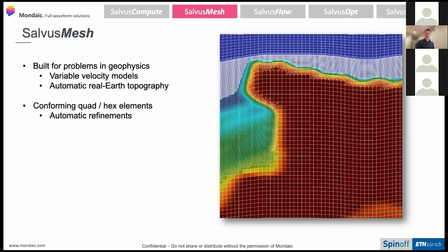And what's also been pretty neat and quite important is this whole focus on local and automatic mesh refinement techniques. So what you're looking at on the screen right now is a classical example that you might have in exploration geophysics, where we have an oceanic layer on top. That's the blue elements that are relatively big. And then we have an extremely slow velocity sediment layer just below the seabed. Now, of course, usually if we want a conforming mesh and we want to ensure that we maintain the advantages of explicit time stepping, we would either need to set the entire mesh to the resolution of the wavelengths that are present in the slow velocity layer, or we can go ahead and just do local refinements to basically not do computational overkill on the entire domain by meshing everything at such a fine size.